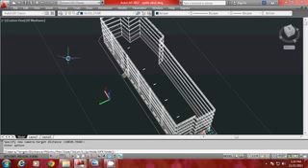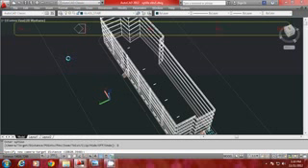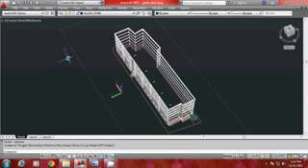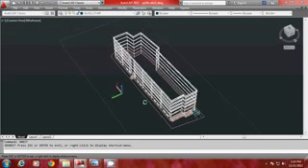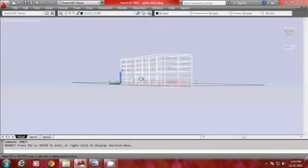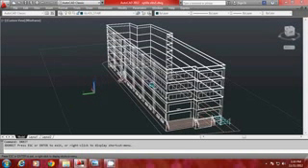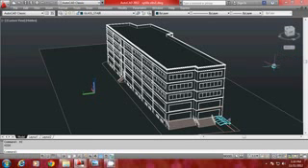Now I would like to increase the distance, so I'll go to distance again and I'll give a higher value. Instead of 18,020, which is the present distance, I'll give a distance of say 25,000 units. Now the camera is moved further backwards, and you can orbit this view. If you want, you can orbit this view to get an eye level view or an ant's eye view. Okay, you have a lot of flexibility in here, and I'll just hide this.